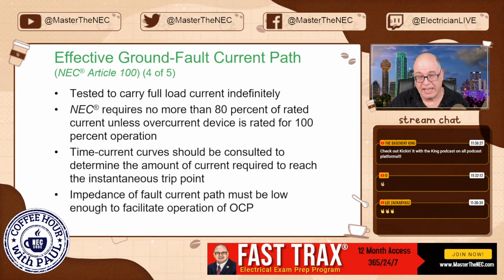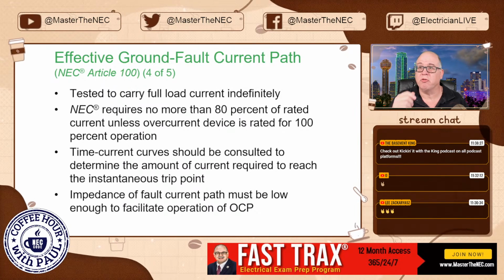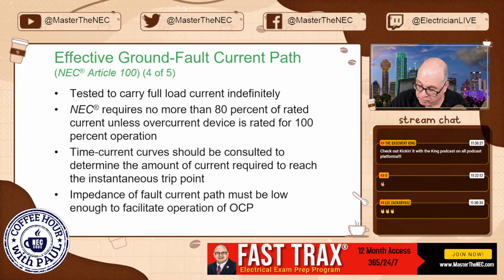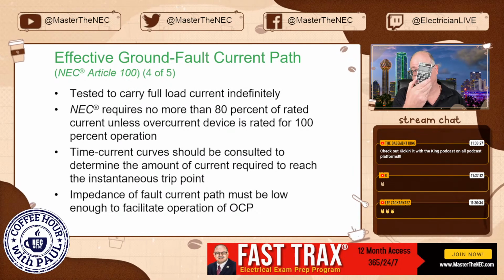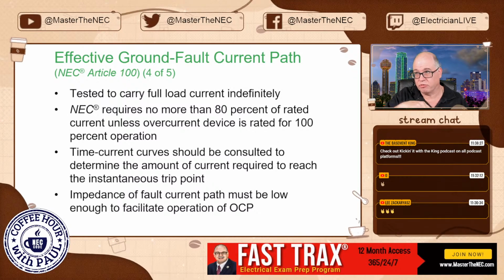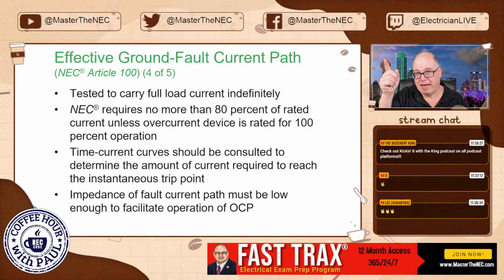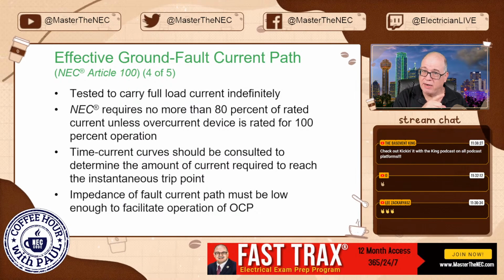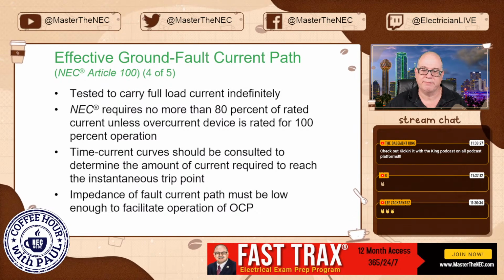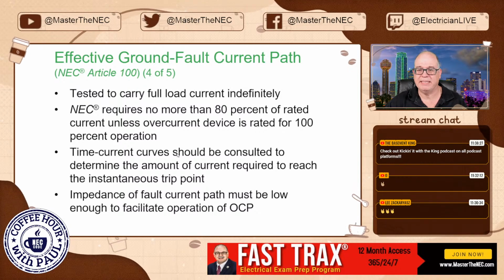If you want to check that, then you go 16 amps times 1.25, 20 amps. So it's multiplication either way. If I know the breaker, multiply it by 80%. If I know the wire, then I can multiply it by 125%. They're reciprocals. There you go. Hopefully that makes sense.